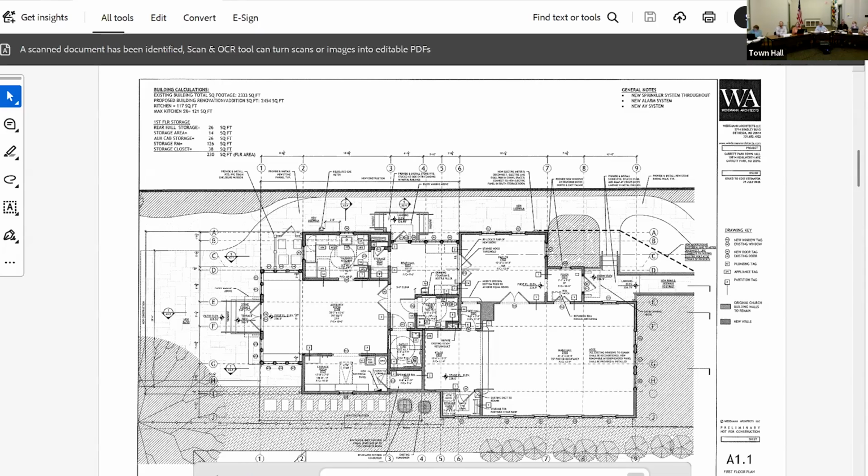When I got your email, I tried to reach out to the civil engineer to get more clarity. There is a distance, I believe it's 100 feet, for the hose to go from the source of the water to the most remote part of the building. One of the connections is going around like this, according to the fire protection plan that was developed. So that must be the rationale. It seems excessive to me, the 4 inch, as does the vault that is required. All I can say is that we'll look into it as this gets developed further.